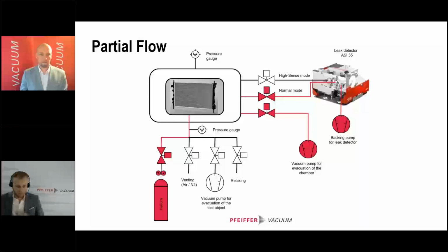And if we speak about the sensitivity, that is more what we mean the sensitivity of the leak detector itself. So this is the same thing as the signal to noise ratio. So when you have a background in the chamber and you have a leak rate that you measure, then this is the sensitivity. I can show you this again on this slide here.